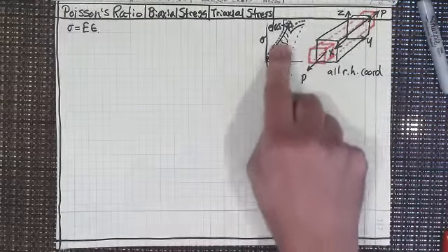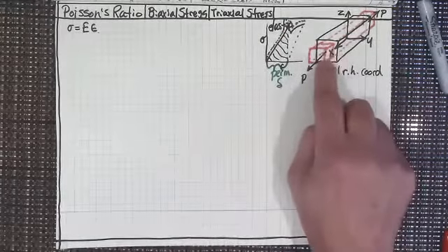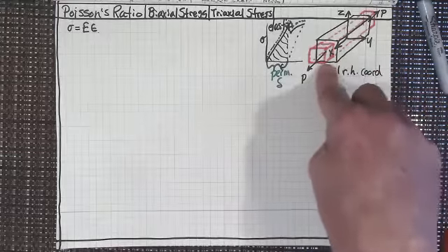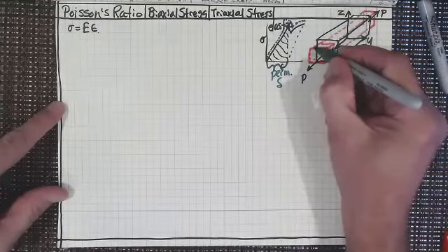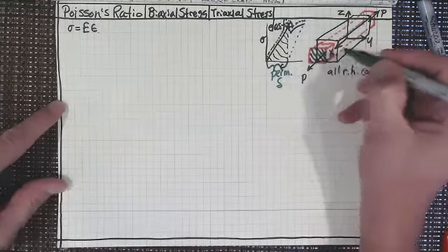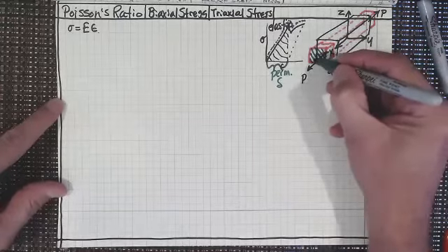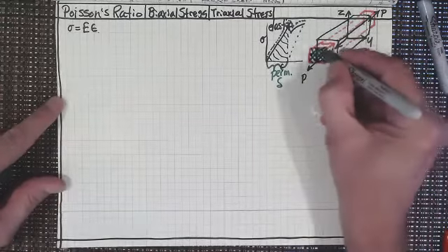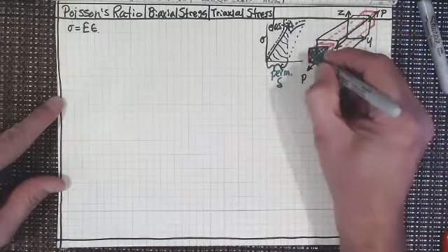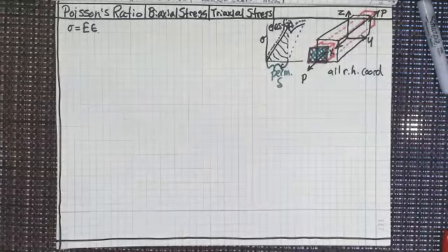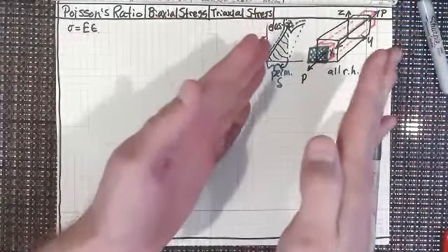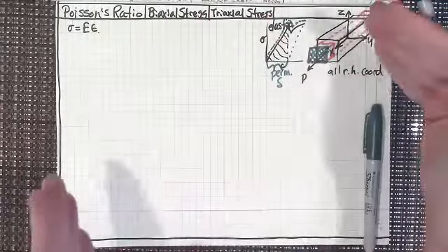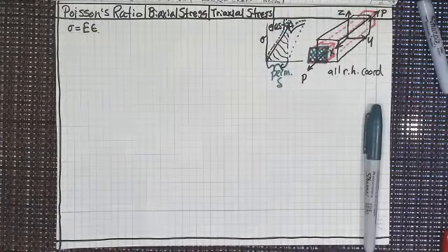The elastic region, everything comes right back. So that's what I'm saying. If I'm staying in the elastic region here, and of course I've exaggerated how much this is going to decrease in cross-sectional area, right? This is going to be the new cross-sectional area. I'll cross-hatch it both ways so everybody can see that, and then I'll outline it. That's the new cross-sectional area, and the old cross-sectional area, of course, is the big black box that we had there. So it stretches out, but it gets thinner. It's getting thinner in both of those two directions, but it's getting longer in this direction. So that's what I wanted to look at.